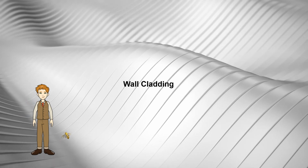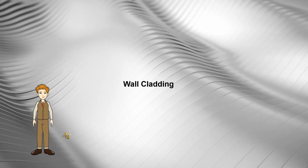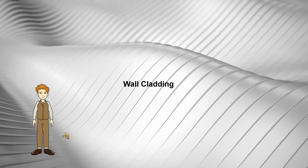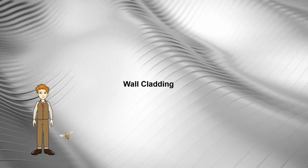Given appropriate attention to joint detailing, wall cladding can be fixed horizontally, diagonally, or in combinations. The range of construction includes, as for roofs, single skin, double skin, and composite systems, with both conventional and secret fastening. Appearance is a major consideration in the selection of the particular type to be used.